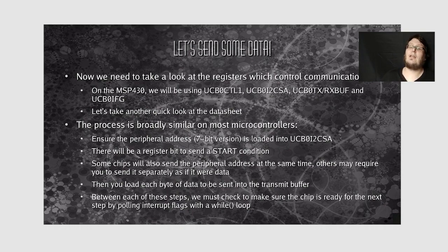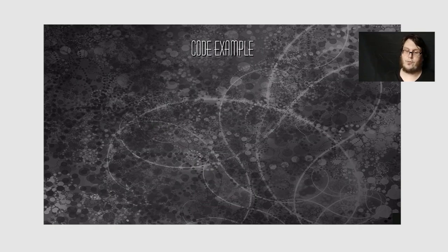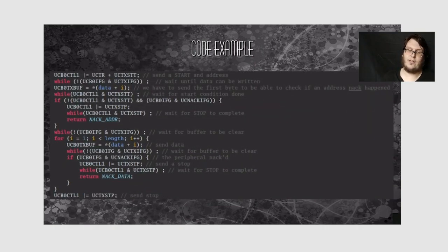So we check to see, is it ready for the next byte? Was there a not acknowledge received? And then we take different actions depending on that. So if we actually go look at our basic code example, this is after everything's been set up.